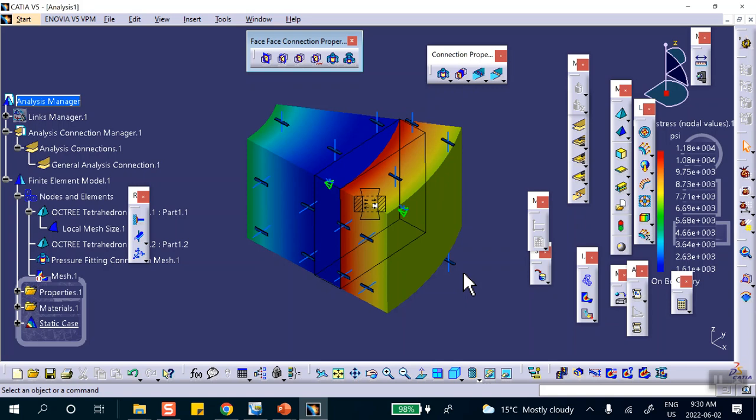This is von Mises stress. Notice that there's a red in the middle because material properties are different. Von Mises stress uses axial stress, radial stress, and hoop stress. Radial stress is continuous, no problem. Axial stress is not 0, but it's some number because I put several sides on. But the hoop stress is discontinuous. That's why there is a big red dot in the middle.